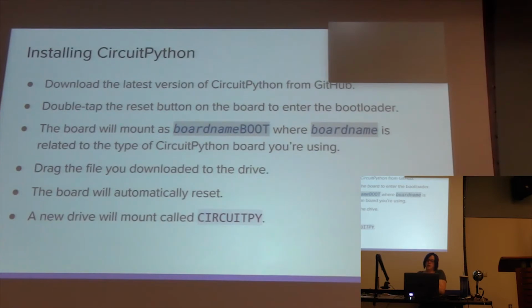To install CircuitPython, you need to enter the bootloader. I thought you said the CircuitPython came installed on the... It does. You may want to update it if you've got a board that's older. It's possible the files on the board can get corrupted if you were to unplug it, for example, in the middle of writing a file. So you may want to reinstall CircuitPython at some point.